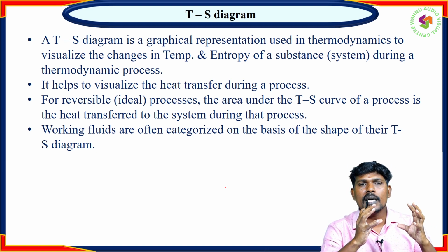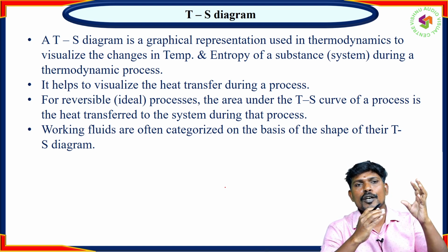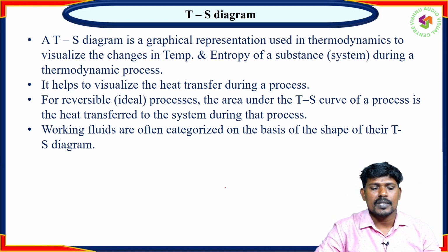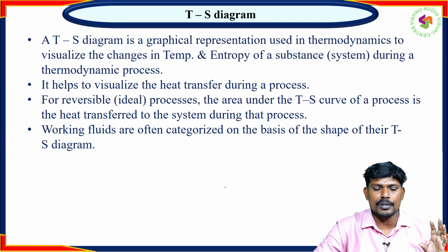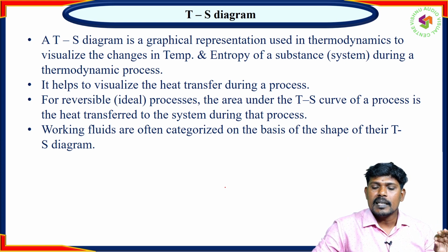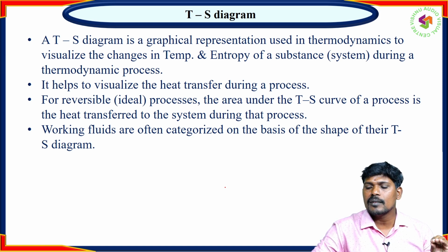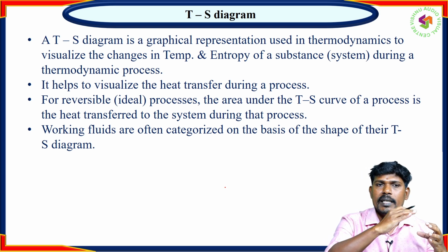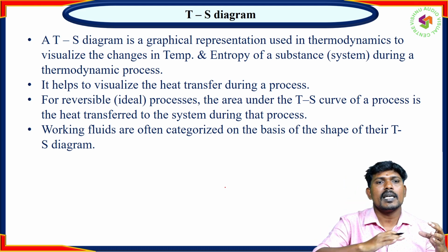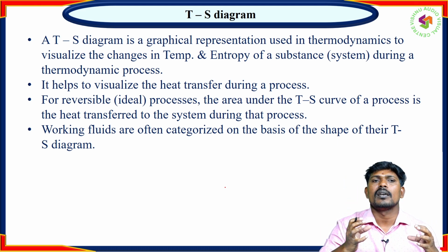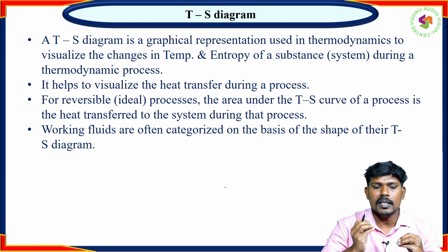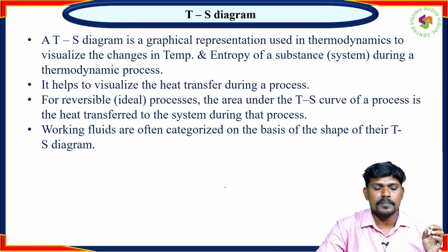We can see, when the temperature of the system is changing, how the entropy is changing. So this is explained by the TS diagram. It helps to visualize the heat transfer during the process. For a reversible process, the area under the TS curve of a process is the heat transfer to the system during that process. Whatever the curve is in the TS diagram, the area under the curve is equal to the work done by the system, or heat transfer to the system during that process.